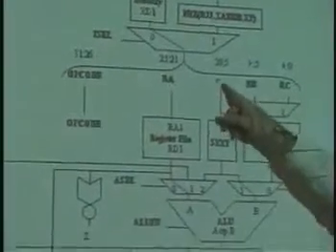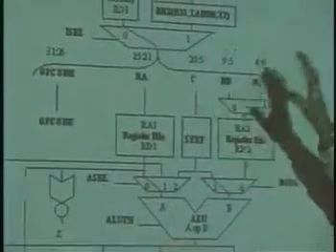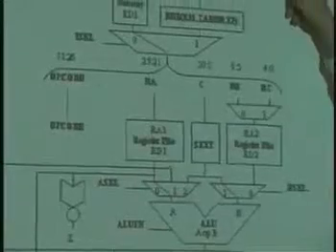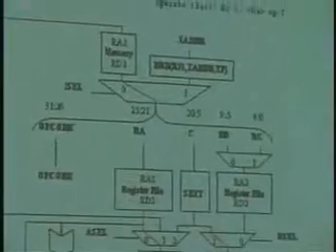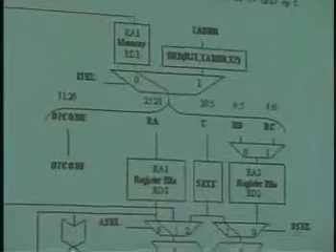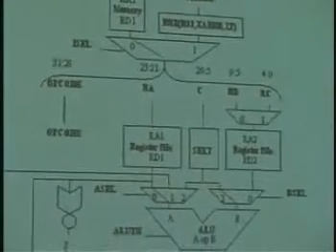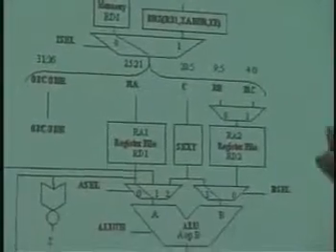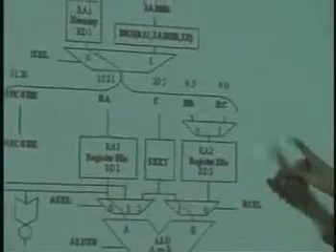And that in turn is going to get the data from C, which is those 16 bits in the instruction word which hold the constant. So this is the way that we're going to handle instructions such as RA op C. In other words, ADDC, register A, constant into register C. So the B select somehow has to be connected to the opcode. Absolutely right. And we're going to talk about the logic that's going to be used to decode the opcode and put out a control for B select, depending on whether the opcode is ADD or ADDC.